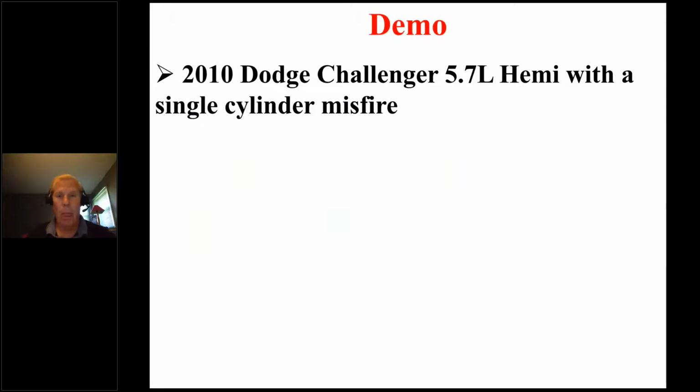Now, what I'm going to do is what I call a live diagnosis. I don't have a vehicle in front of me, but I have some Pico screens saved from this particular Hemi. So this is not in the handout, but I want to give you an idea of how some of these measurements are being done. I'm going to try to accomplish a few goals with this example. So we have a 2010 Challenger 5.7 Hemi with a single cylinder misfire. And please take my word on this, the diagnosis has been done to the point that we suspect it's mechanical.